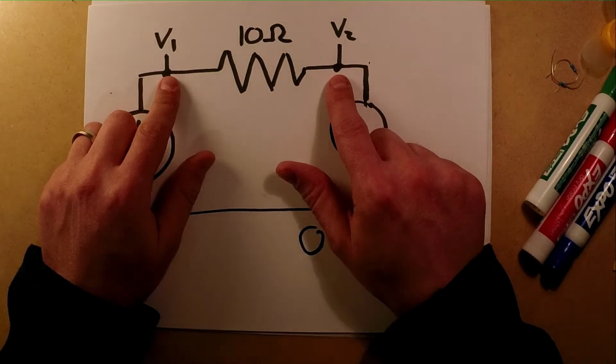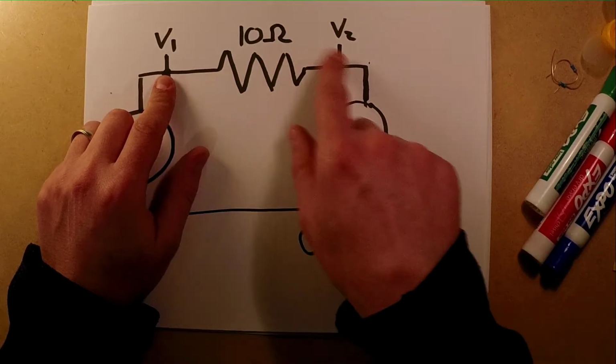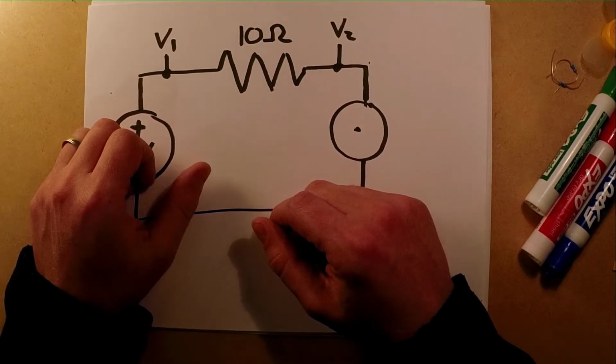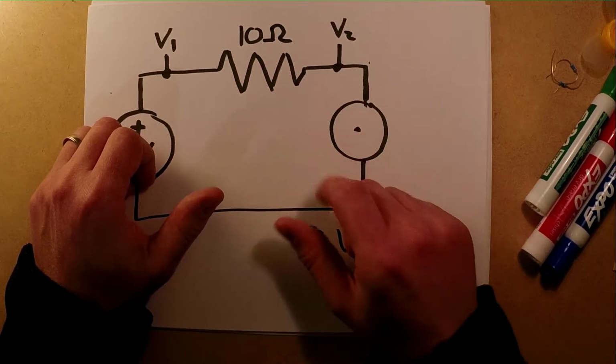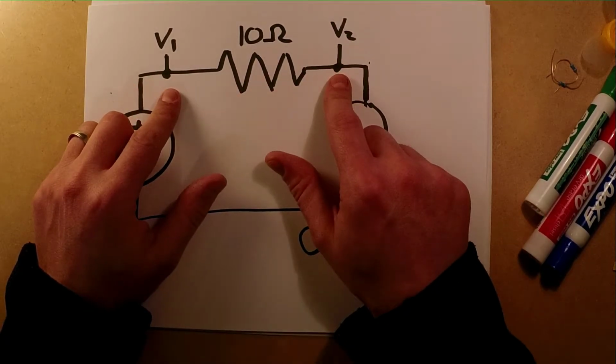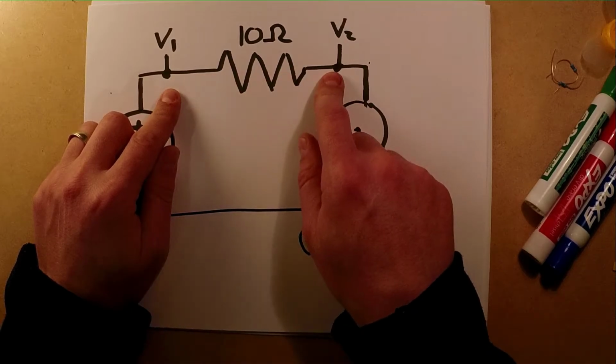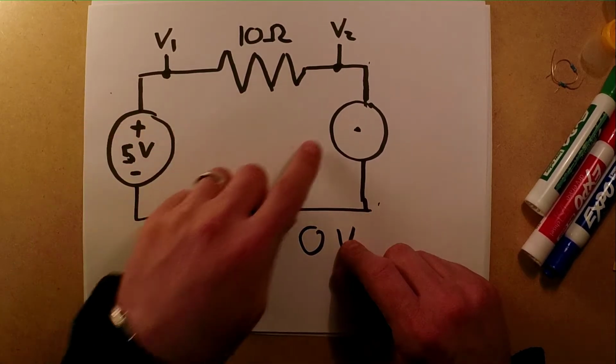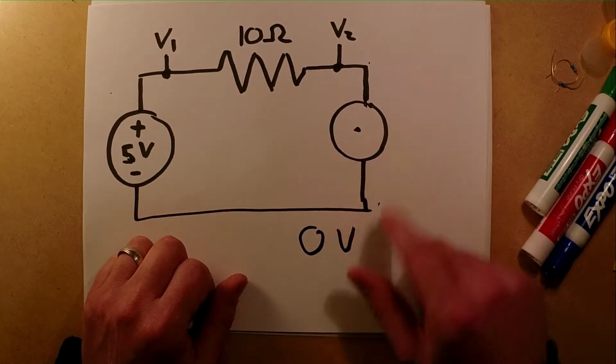If we measure the voltage drop across this 10 ohm resistor, this is the circuit you will actually be building to measure the power consumed by your motor. If we measure that, then we know the current flowing through this resistor, and we can also get the voltage drop across the motor. This is the motor in our circuit here.